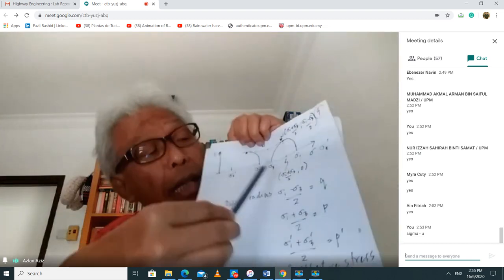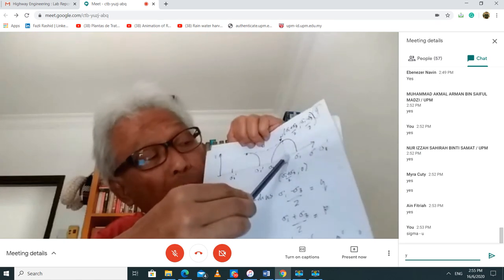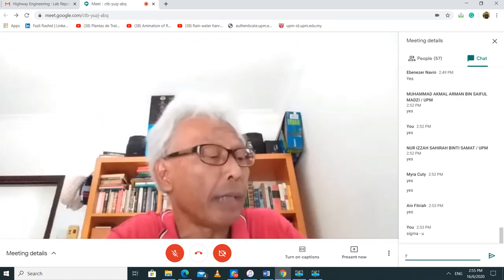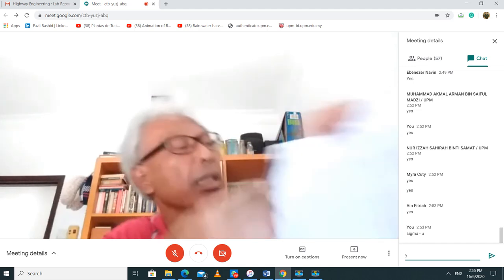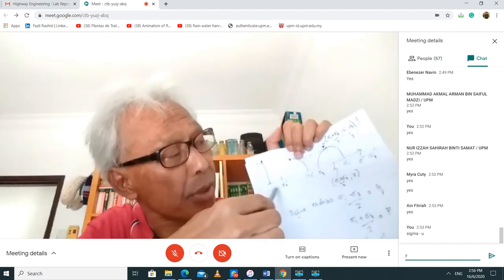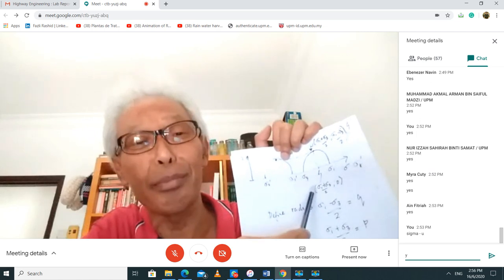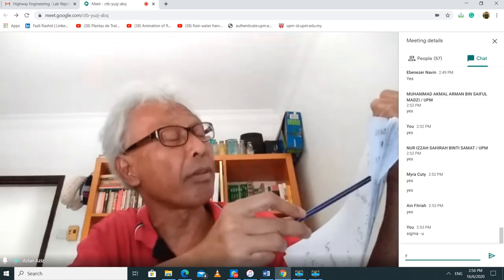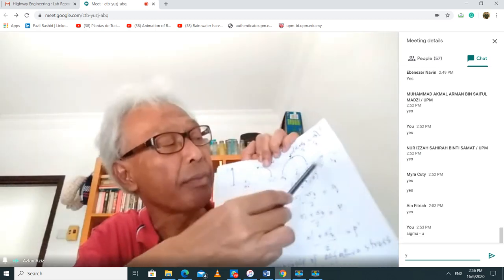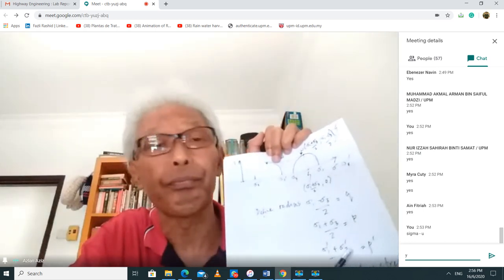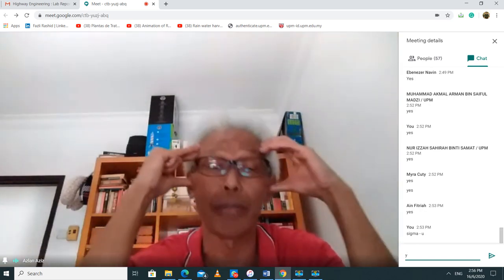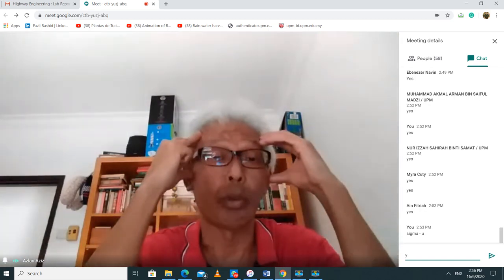Okay, now there is the x coordinate for this point here. The x coordinate for that is going to be sigma 3, the distance from 0 to this point here, sigma 3. So it's going to be sigma 3 plus the radius of this Mohr circle. The radius of that Mohr circle is going to be sigma 1 minus sigma 3 divided by 2. Okay or not?